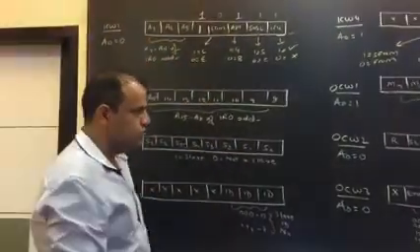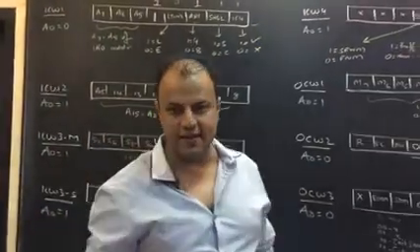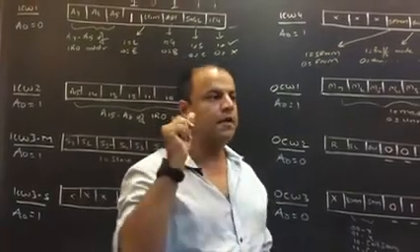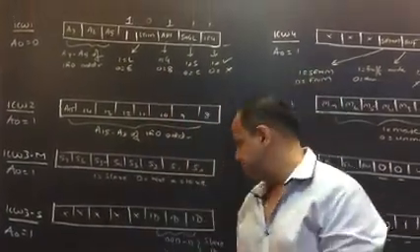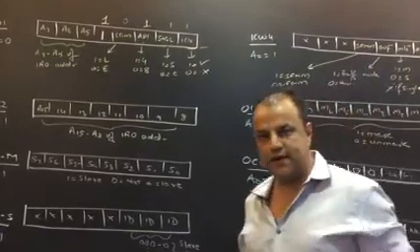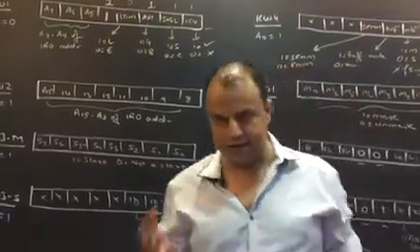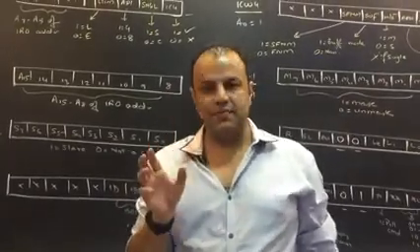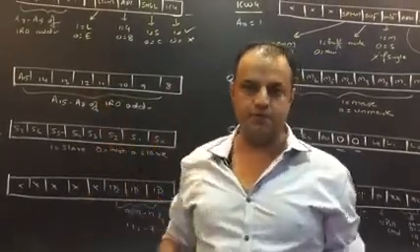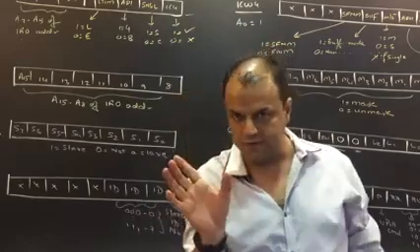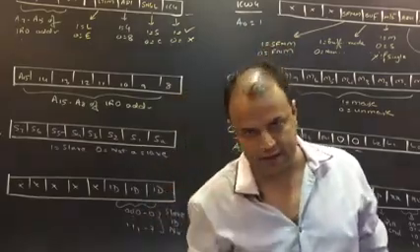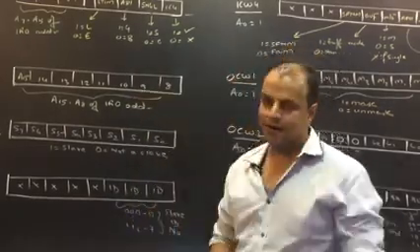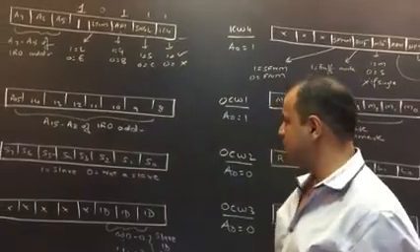Now, you don't give all ISR addresses. You only give the ISR address of IR0, correct? In that also there is an issue. An ISR address is a 16-bit address, correct? ISRs are stored in the memory, so the address will be a 16-bit number. Now to give a 16-bit address, each command is 8 bits, so your address will be given using 2 commands, lower byte and higher byte, correct or no? So they will take up 2 full commands now. Instead of doing that, they used a very smooth idea over here.